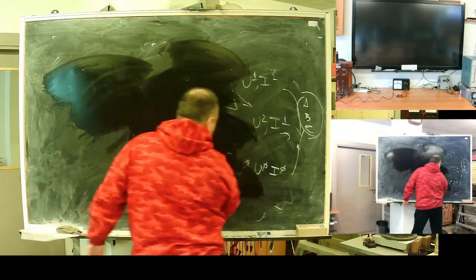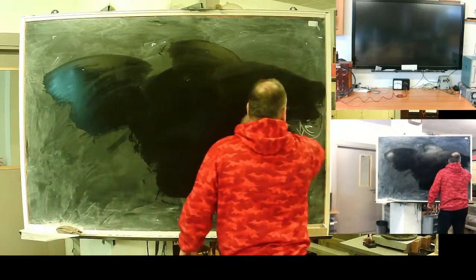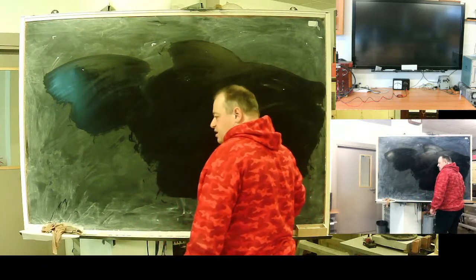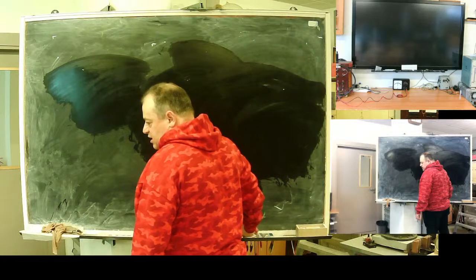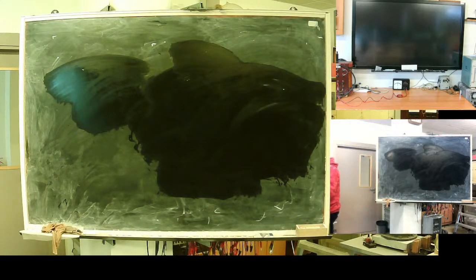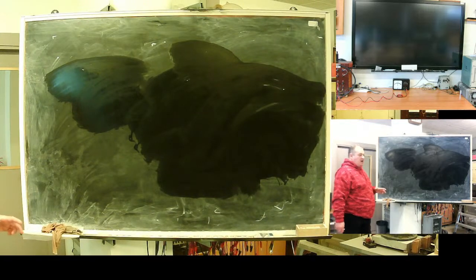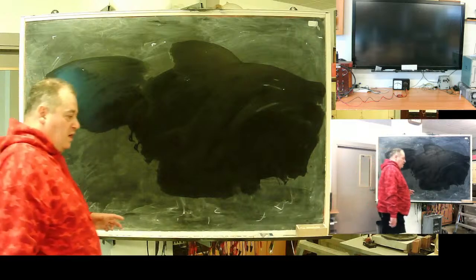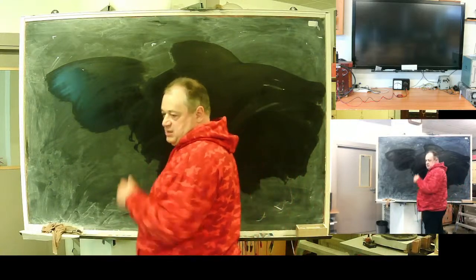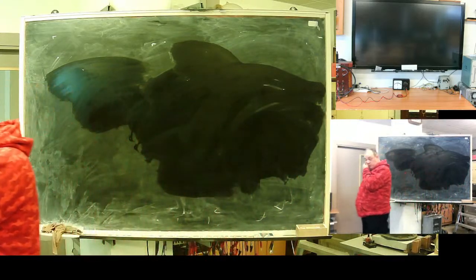The technique of symmetrical components assumes that real is a superposition of ideals. This is at the very base of the technique, an extremely important concept. We can speak of superposition, or real is a sum of ideal, only if the real network, our network, is linear: if resistances are constant and current is always proportional to voltage.